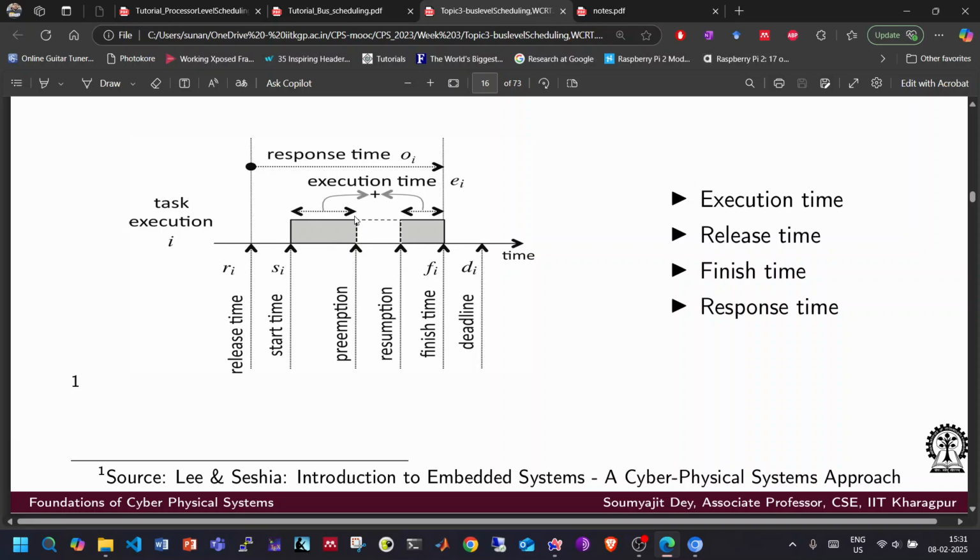Now there are different ways to handle task executions. This is a very generic picture. One way to handle it would be, if I see something more important is coming, then I will stop execution of this particular task and preempt it with some other task. This is called preemption, preempting with some other higher priority or higher criticality task that needs my attention right now. When that is done executing, I will restart this task from where I paused it. Obviously the program has to be written accordingly, so that it starts from the checkpoint up to which you executed the task.